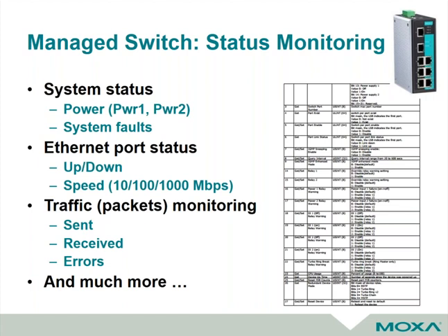And how about some useful things? How about if you have a redundant power supply, the status of both of those power supply inputs, and you can kind of see how pull response like Modbus is kind of similar. How about if one of those ports on that switch, you guys have all seen the little green blinky light on the back that means you've got something connected, and you know that if that light is not on, you've got a bad cable or the device at the end of it's not been powered up. What if you could monitor that remotely? What about seeing traffic? And what about seeing errors on that traffic? There's a tremendous amount of information in these switches that could help you more easily troubleshoot these things.